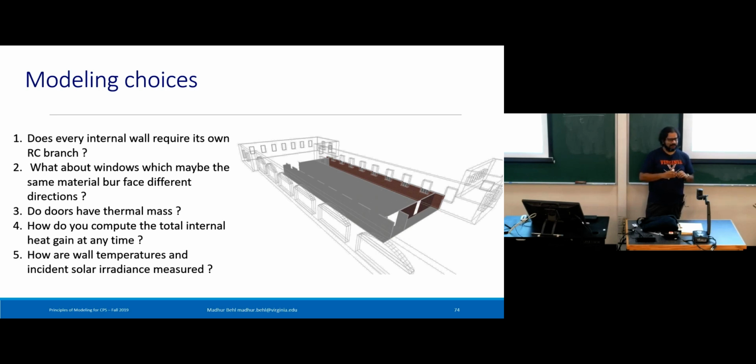A luminance sensor has the correct principle, but it's only sensitive to the visual range. So you need something similar. Let me repose the question: what type of sensor is a luminance sensor? What actual sensing element does it use? It's a very simple element, actually. You just have materials whose resistances change based on a particular spectrum of light. In a lux sensor, it's called an LDR, a light-dependent resistor, or an array of light-dependent resistors. Based on the intensity level, the resistance will change.